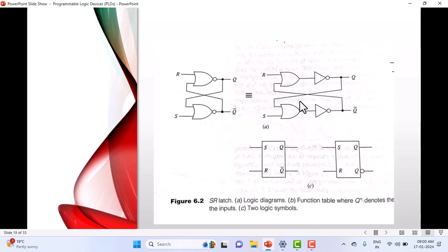This is, in fact, a combinational circuit only. Why am I saying this is combinational? What is our definition for a combinational network? Output depends on input. So here the Q and Q bar outputs depend on the input. Understand? You change the input, the output changes. Because there is some delay here, two gates, one level of delay from input to output. If I assume a 10 nanosecond delay for each of these gates, then after the 10 nanosecond delay, whatever input you apply, depending upon that, the results will be produced. Understand here? It's a very simple combinational logic circuit here. Okay.